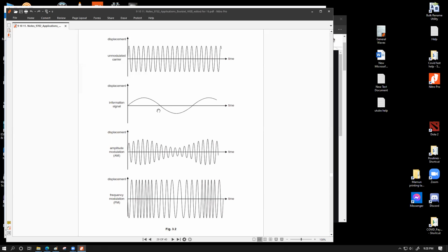So what do you see? You should be able to understand what is being altered. There are a couple of things that I'd like to draw your attention to. Mind this information. Whenever we merge the unmodulated carrier signal with the information signal, in the process of amplitude modulation, in no case does the amplitude of the modulated signal become 0.